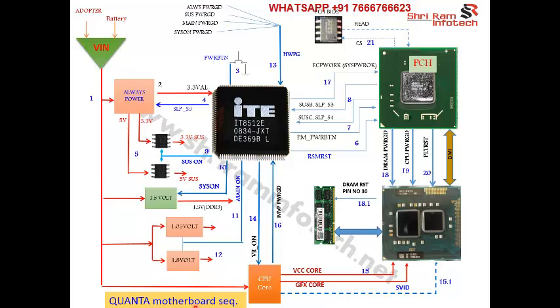Now each section has its own power good. The power good signal means every pulse width modulator has two signals. One is the input, another is the output. Input signal means the enable signal. This is a 3 volt signal. It's called the enable signal. And once that section is okay and ready to work, at that time this particular pulse width modulator sends out another signal called the power good. The power good signal means that particular department is saying my department is okay, is working fine. It's like an acknowledgement.